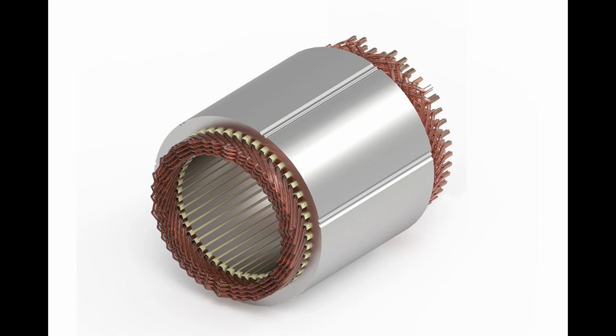In summary, rectification is the process of converting the alternating current, AC, output of the alternator into direct current, DC, using diodes and a bridge rectifier. This converted DC is then used to charge the vehicle's battery and power its electrical systems, providing a consistent source of power despite the fluctuating nature of the AC output from the stator coils.